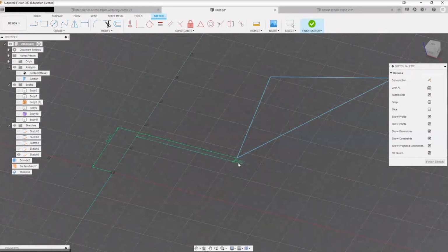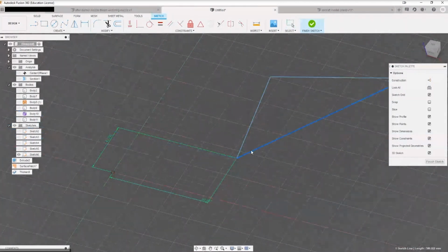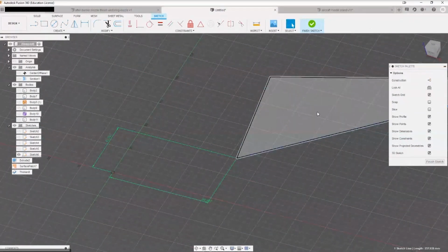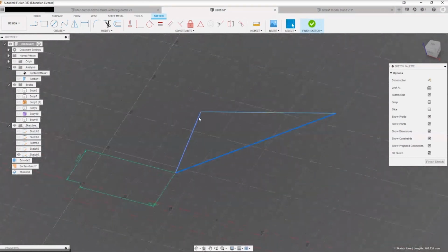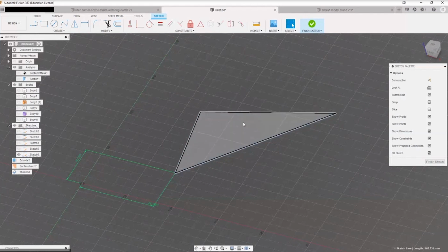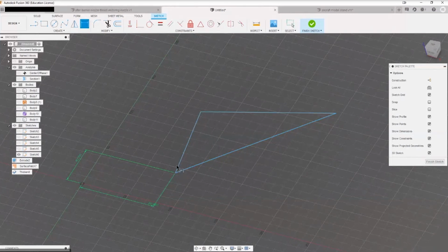This point is not going to move anywhere. All right. So you can see I'm trying to drag this component out, but it's staying fixed around that point. Before, it would just move out parallel. Okay, so that point is constrained. So there's three different ways that you can do it. You can constrain all three points, or you can be a bit more neat and constrain this angle, and if you've got a specified distance, depending on your design, you can hit that.